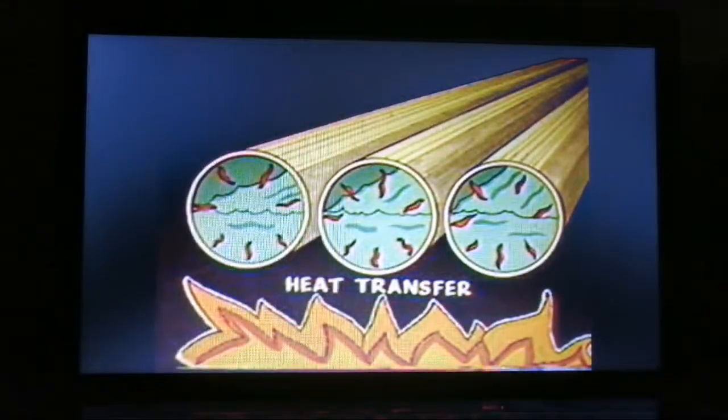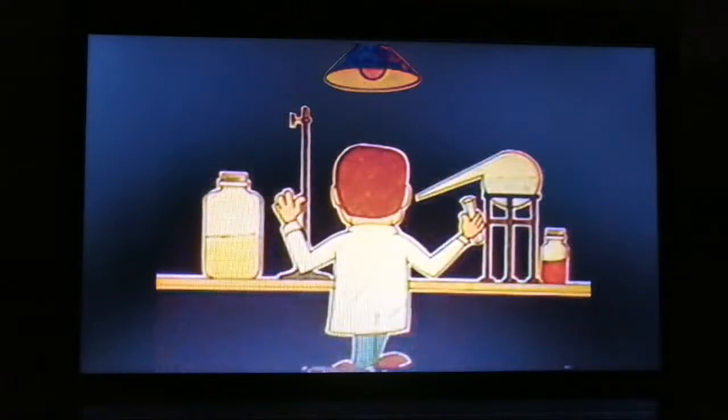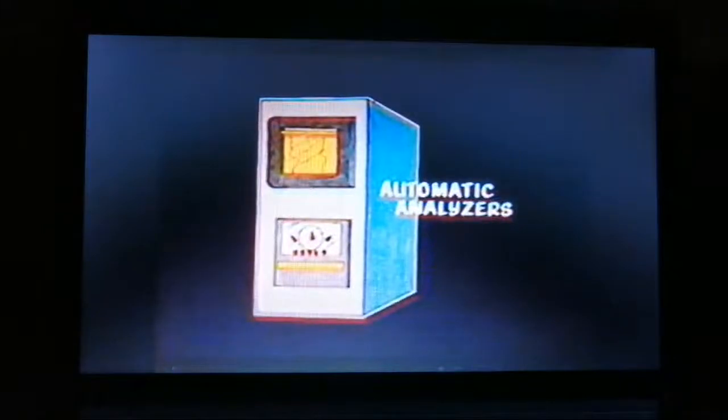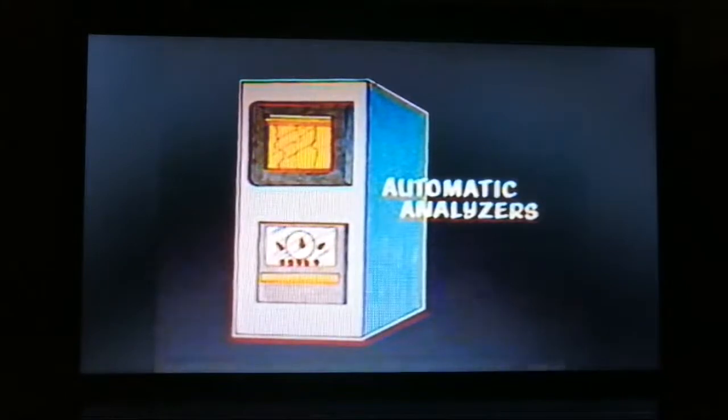But along with proper burning of fuel, effective transfer of heat into boiler water is important. The water in these thousands of pipes must be free of dissolved materials, which can form hard-scale deposits inside boiler tubes. These thin crusts of minerals act as excellent insulators, blocking rapid heat transfer to the metal. At one time, most power plants had a chemical laboratory which made frequent tests on boiler water, feed water, and condensate to be certain water stayed as pure as possible. Today, most labs have given way to automatic analyzing instruments which continually sample, analyze, and indicate the chemical condition of water from several sampling points.